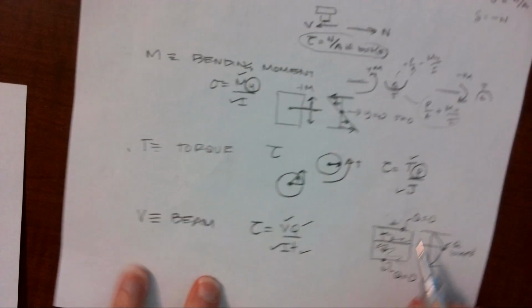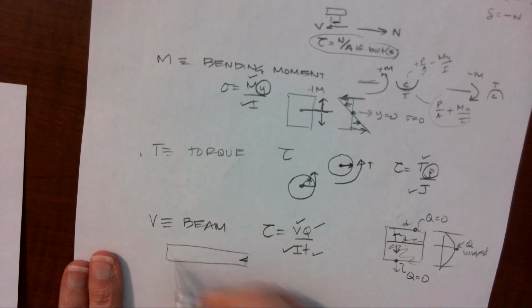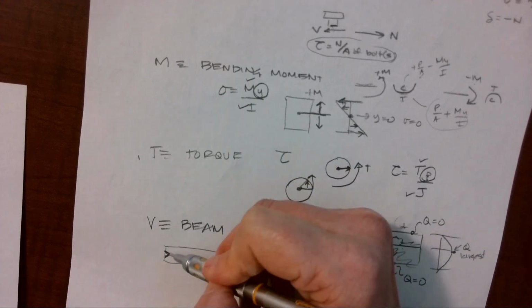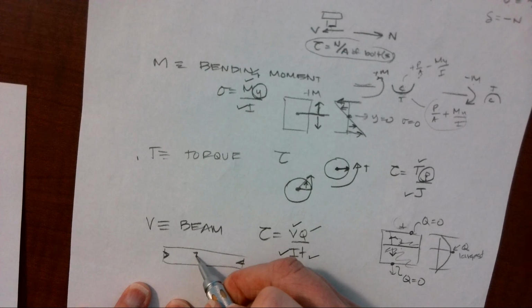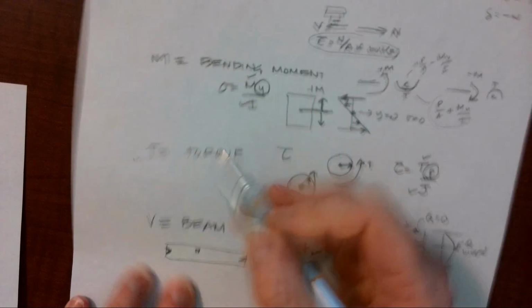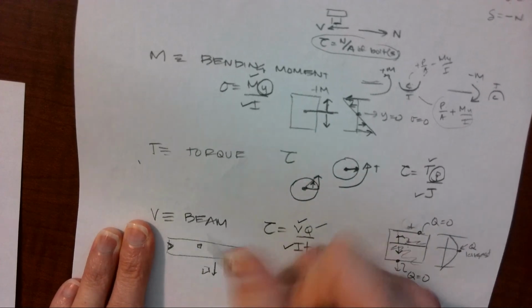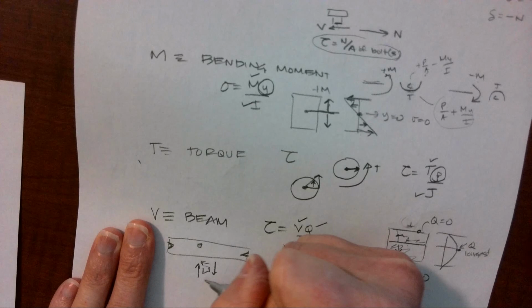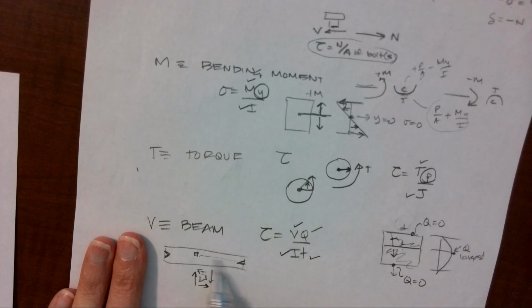And that's why if you see giant wooden beams, you might see some separation right here in the center where your supports are, because that's that longitudinal shear that's happening. So if we were to take a little tiny element out, and I were to look at the shear happening on that element, for static equilibrium I would also have to have a shear equal and opposite on the other side. That causes spinning. So we need this longitudinal shear to keep that block. So this longitudinal shear is what we're looking at when we are looking at beam shear.